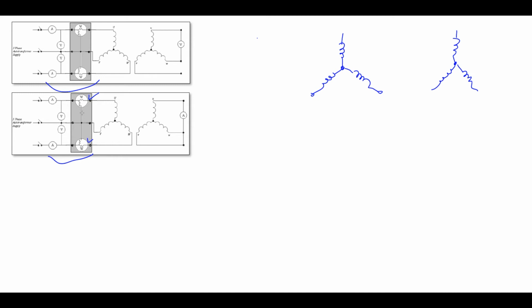We can add the displayed powers, and this will give us the total power at the input of this transformer, and we measure the current using an ammeter and another ammeter here. So two voltmeters and two ammeters to measure the current flowing in the first winding and the voltage across the two windings. This will display V line to line, and this is the line current.